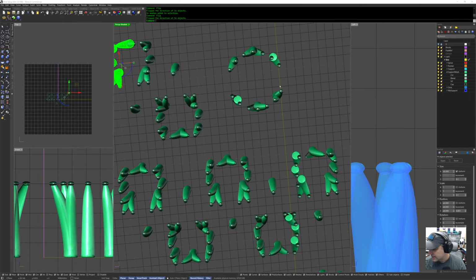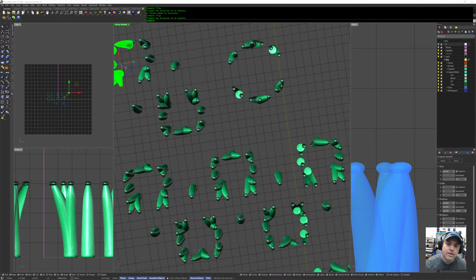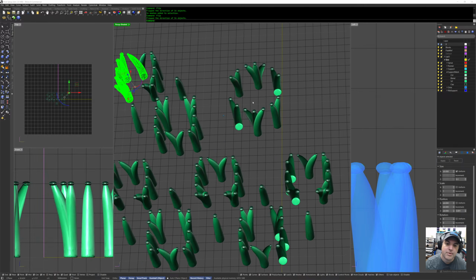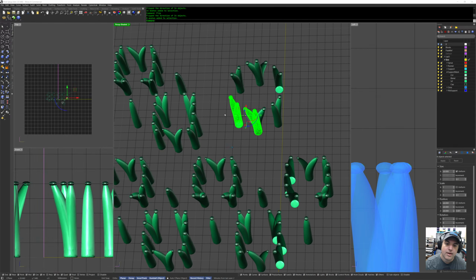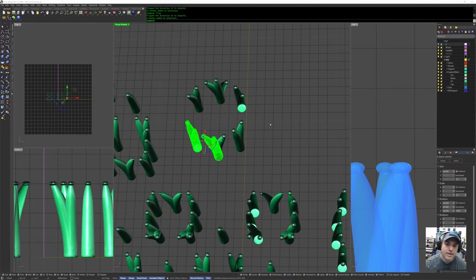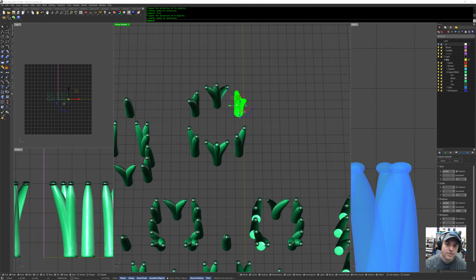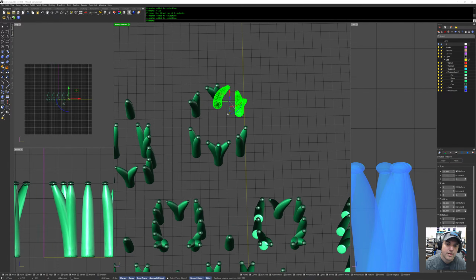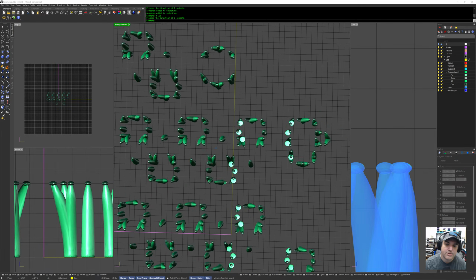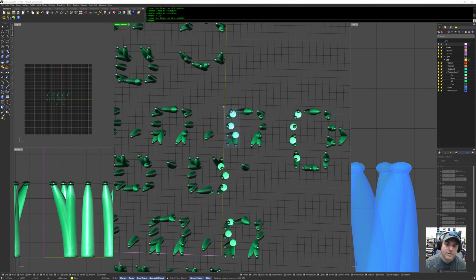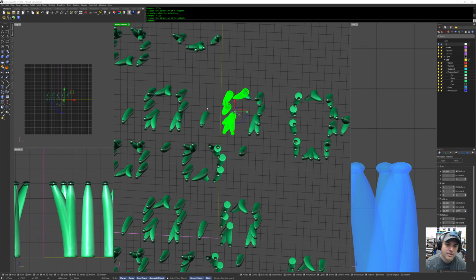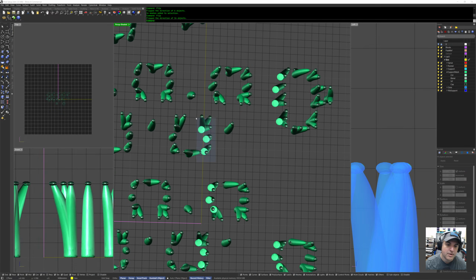No, I am not going to take it back to 3D coat. The tolerances I have built in here for the pins and the rivets, I'm not going to let it risk doing a smooth all. So this is straight to the printer. That's why, instead of making the sprue just a flat, I gave it a little bit of a fillet so we'd have good metal flow.